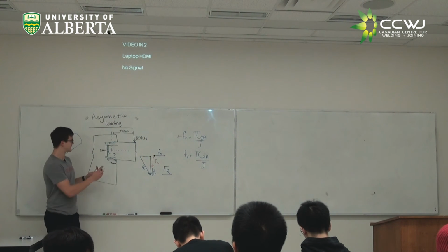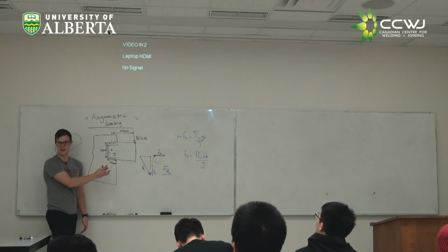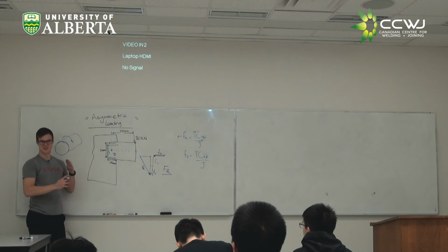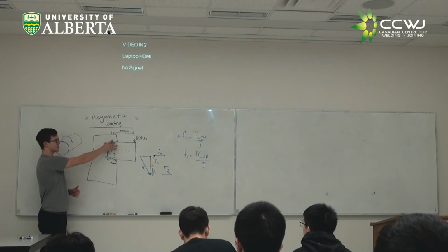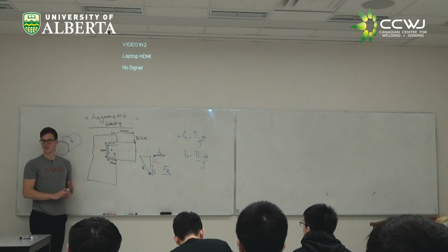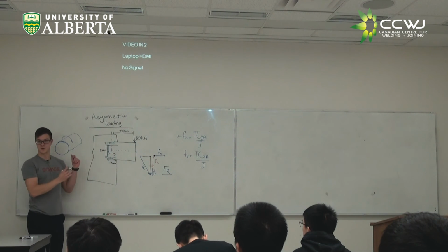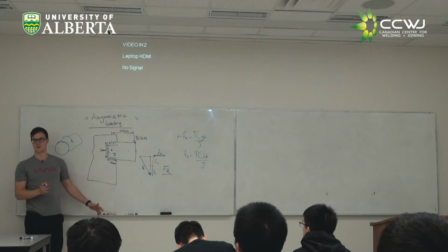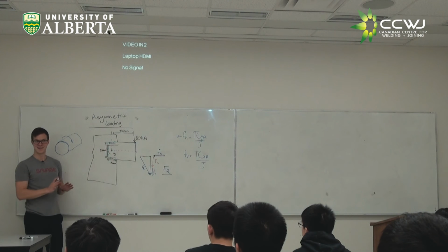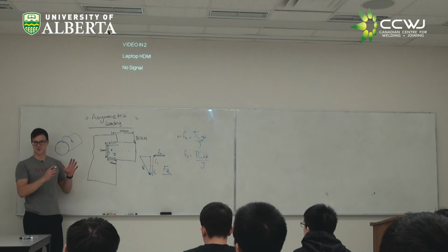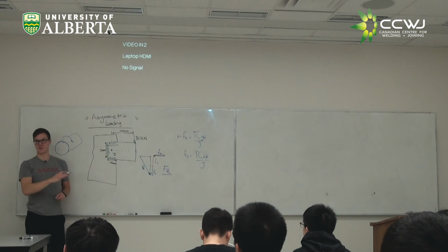Now, once you get this force, we talked today a little bit in class, because in this component we see we've got a force going this way, and in this component the force is going this way. The angle of this force is not necessarily something that's easy to calculate. That's why we said when you start to look at how this load is acting with respect to the angles of these welds, it's a much more complicated mess. So the American codes, or the handbook that we were going off of, they don't even worry about the MW and the sine theta term. When they get to this sort of situation, they say, okay, we're not going to give ourselves extra credit for having a transverse weld. We won't go up to 1.5. We're also not going to knock down that 0.85.